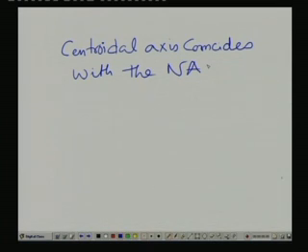So, what this idea tells us is that for a given cross section of a beam under bending, the neutral axis is always the same as the centroidal axis of the cross section. This is one very important conclusion and one should keep a note of it.